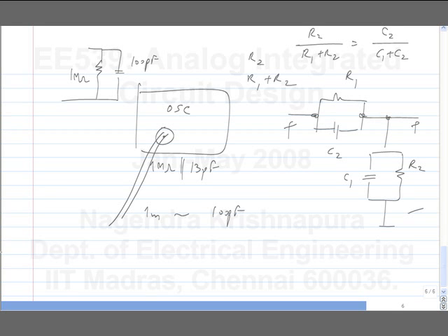Okay. And you are familiar with the times 10 mode of the oscilloscope, X10. Sometimes to reduce the loading on the circuit, now this 100 picofarad will load this circuit a lot, perhaps. So to reduce the loading, or alternatively to measure high voltages, your oscilloscope measures up to 20 volts, you want to measure up to 200 volts, you can connect 9 megohm resistors in series. But this voltage division works only for DC, right? For AC, what happens is, because of this capacitor, you will have a low pass filter between this input and the oscilloscope input. So you also connect a capacitor between these two.